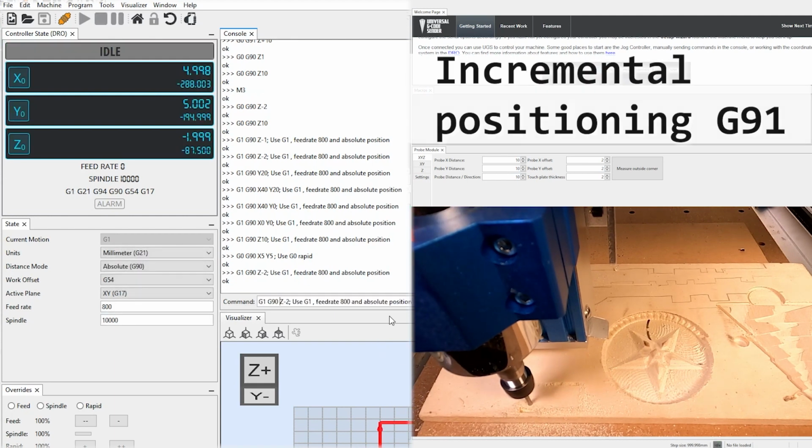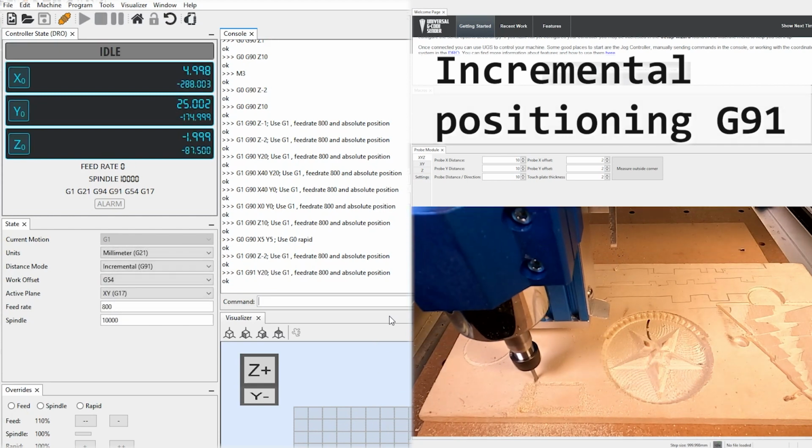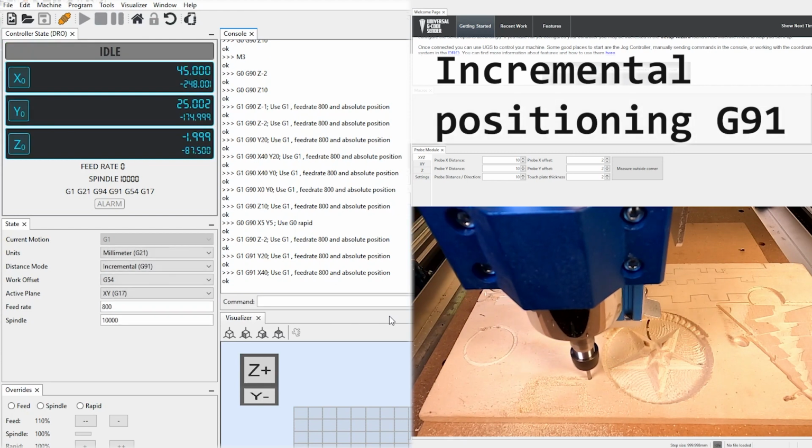Again, we will define the next endpoint as a parameter using GCode G01, but now as a relative distance from the current position. The CNC controller will then move the machine to the new calculated endpoint in 3D space using a linear motion.